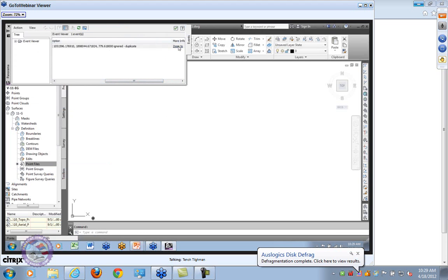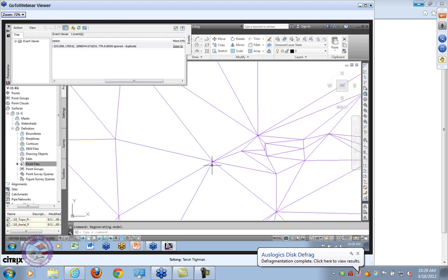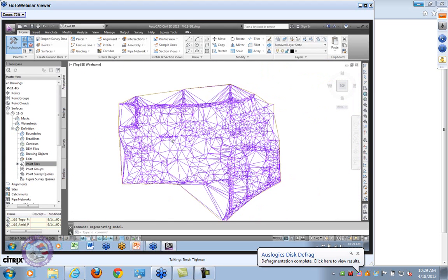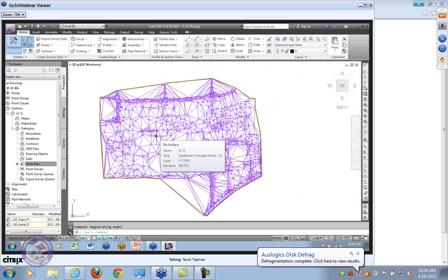Okay, so now it says paint, got all my points, right? And there are 2 points in the same location, and this is just a fast way to get to my surface model, right? In both files there was a common point, and it better be. One of my questions right away was how come there weren't like 5 or 6 common points between what the surveyors went out and got, and at least the crosses should be there. But well, maybe we thinned all that out. And so we get a classic TIN model. This is a great way to visualize what's going on.